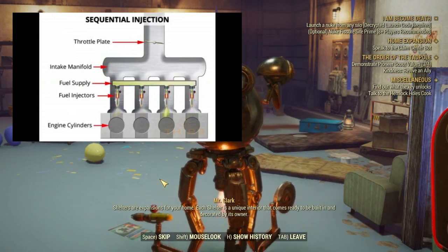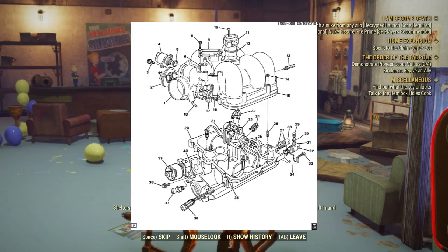For example, in GM trucks, and I'm sure a lot of people who have or have had older Tahoes, Suburbans and Blazers know about this, the spider injection. It basically was this block that would take the fuel, and it had a bunch of small skinny hoses coming off it, and those would be the ones responsible for spraying it into the intake, and from there it would go into the combustion chamber.